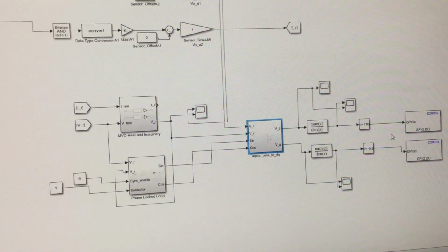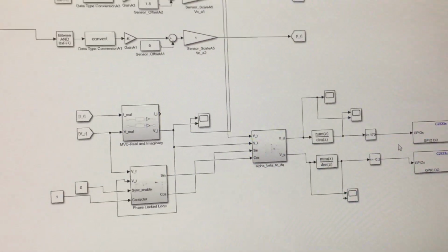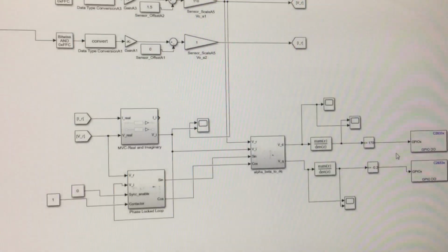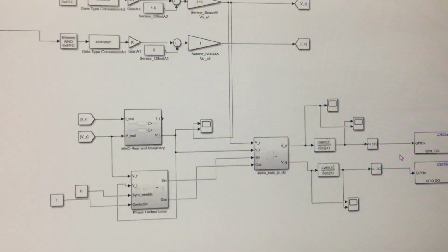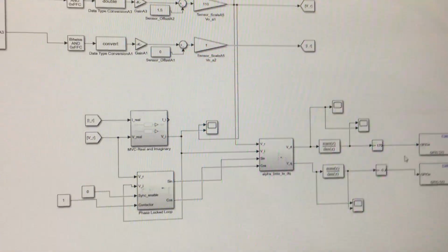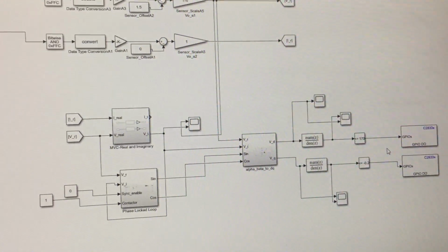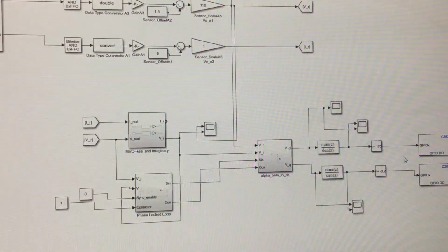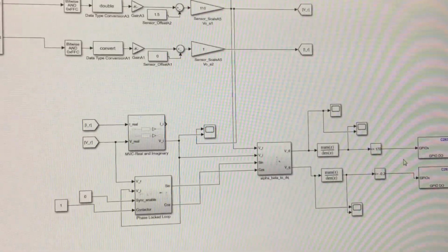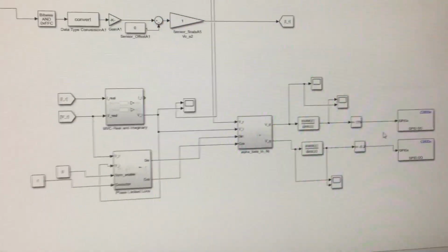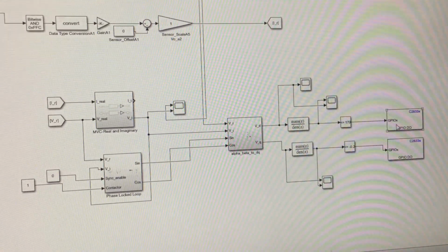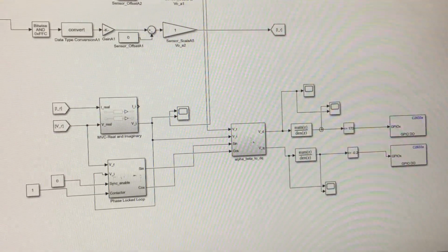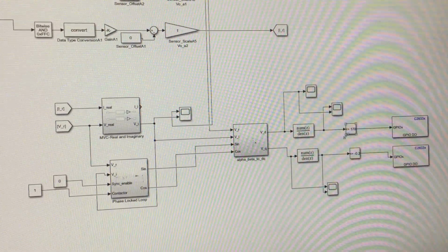Now the question is how can you see your DQ frame? One method can be easily performed by getting the internal values of the registers in Code Studio, or you can record the data by making use of the SCI transmission block. But you can also make use of the GPIO digital output pins by comparing your values with an appropriate constant block.